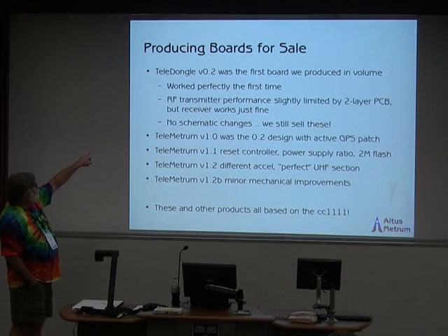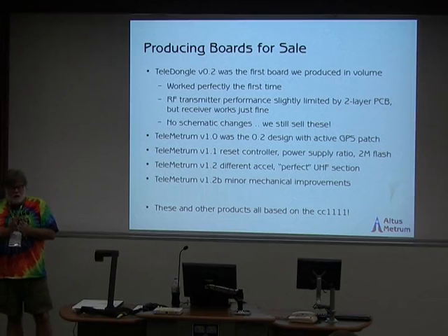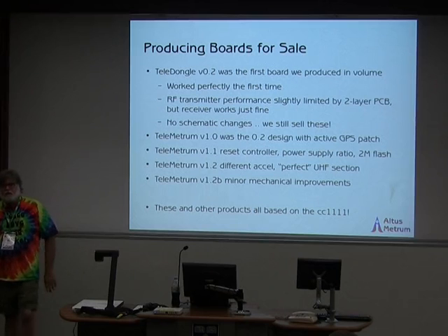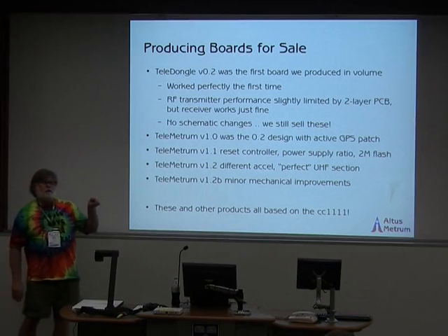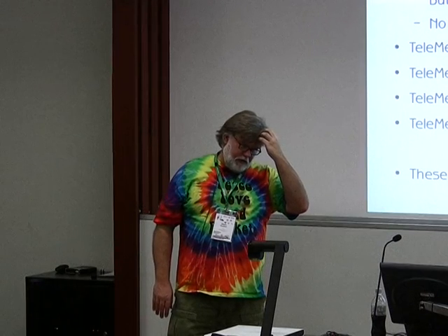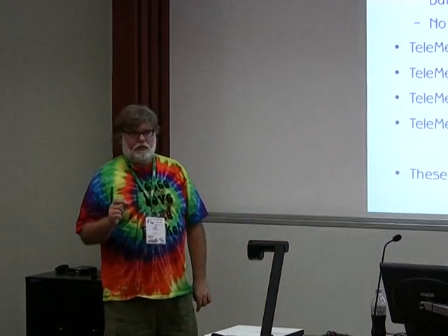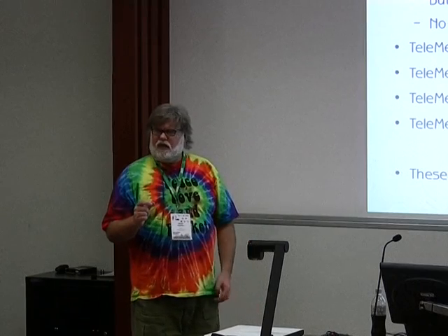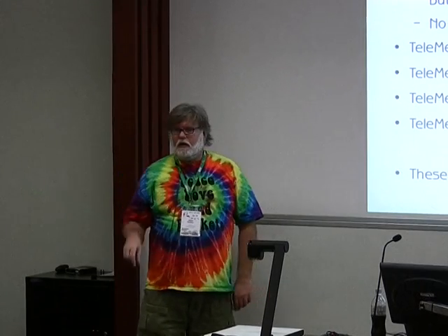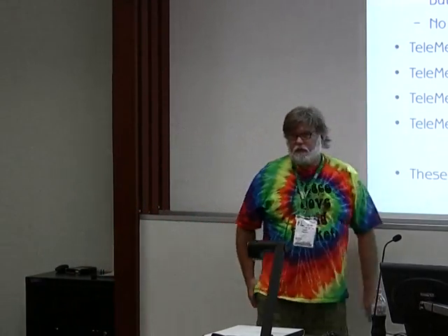So anyway, the issue is that you cannot achieve a 50 ohm impedance trace on a board that thick with a ground plane on the back side of the board without making the trace crazy fat. I hate trying to do these conversions in my head with not enough caffeine. The trace width has to be in excess of 1/10 of an inch, so that works out to be like 2.5, getting close to 3 millimeters wide. It's too big.